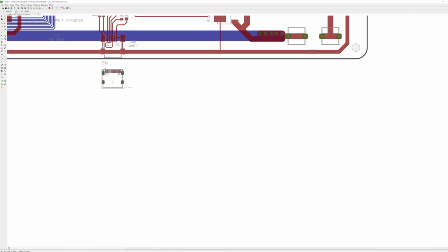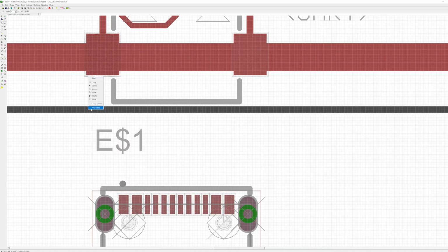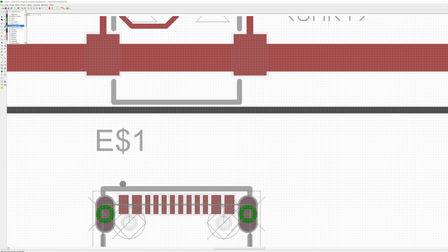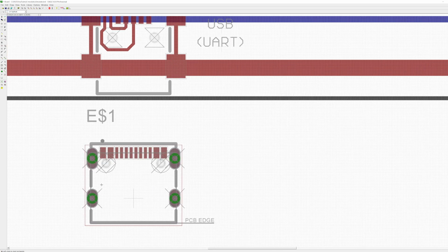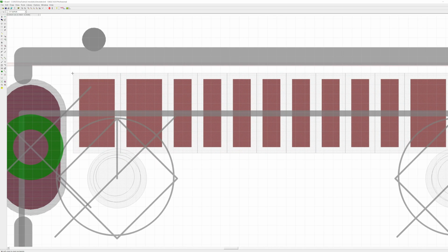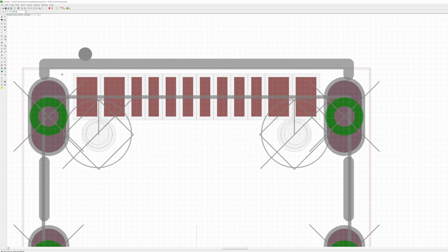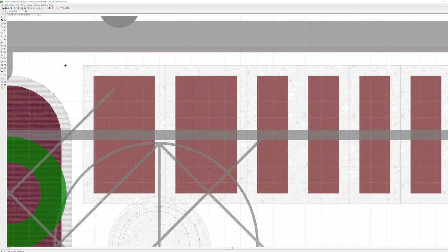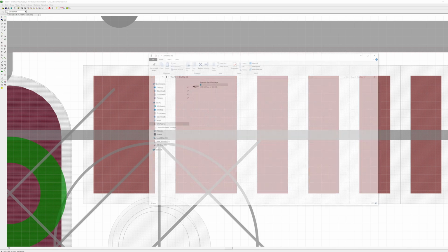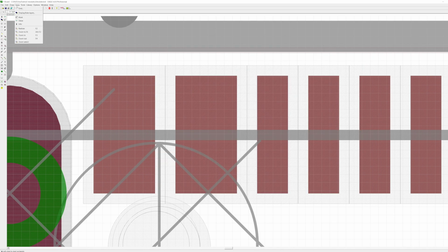Now let me remind myself of what layer this is, for example. So this is top mask. And instead of doing individual top masks, I could probably just do one, but I'm noticing that the grid isn't lining up with these very well, so I'm going to have to shrink the grid yet again. So half of 625, that would be 312.5, which would be that. And it's still not quite lining up. Let me see if I can shrink the grid one more time.